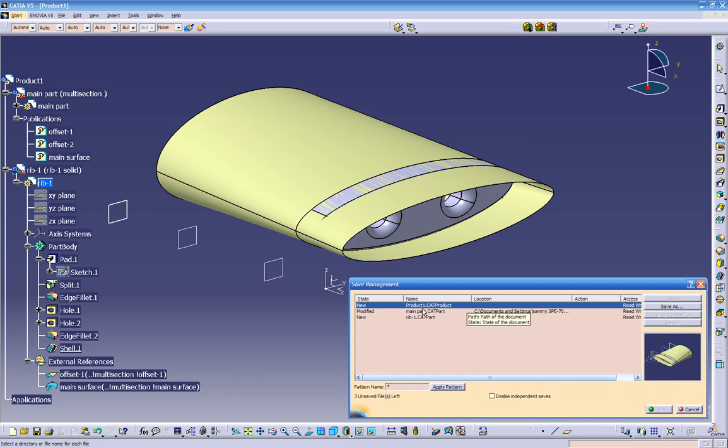We have to make sure every time we save those files, they always have to be under the same folder. Because if you're trying to open the CAD product alone and it doesn't know where those files are, you won't be able to open it, and it's asking, hey, where's the location? So I always make sure to have a folder for each assembly individually. Like you saw me earlier, I'm going to save all this in the same folder.